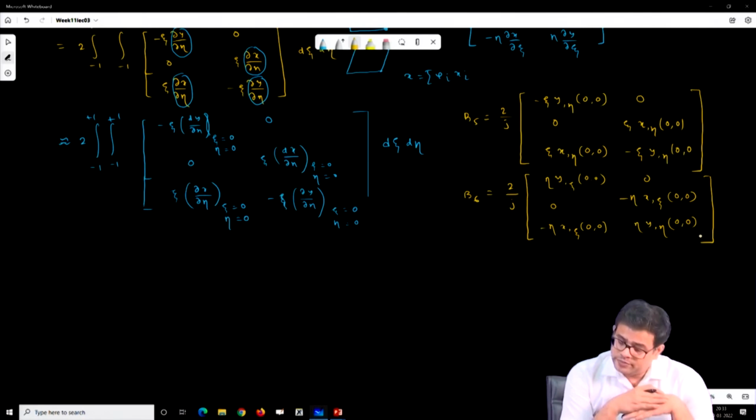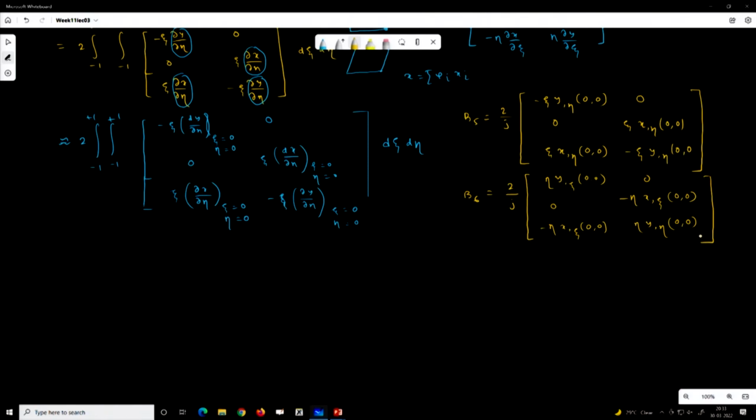However, these incompatible elements, from the basics that we have studied, this very basic incompatible element, are very helpful in capturing the bending mode in the lower order element. Now obviously this ad hoc incompatibility actually creates a variational crime, and naturally it is not variationally consistent in the procedure.